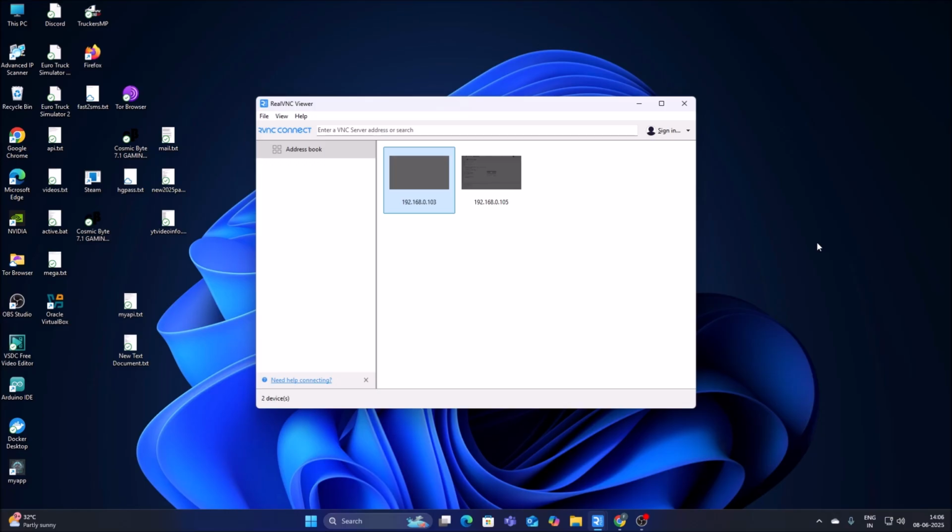We will first create the data using a Raspberry Pi 4 camera module. Okay, we will capture the images. We will send the images using SCP to our Windows machine. Then we will label the images, and then we will send the data to a Google Colab machine, and we will create our own TF Lite or MediaPipe Lite model for Raspberry Pi OS.